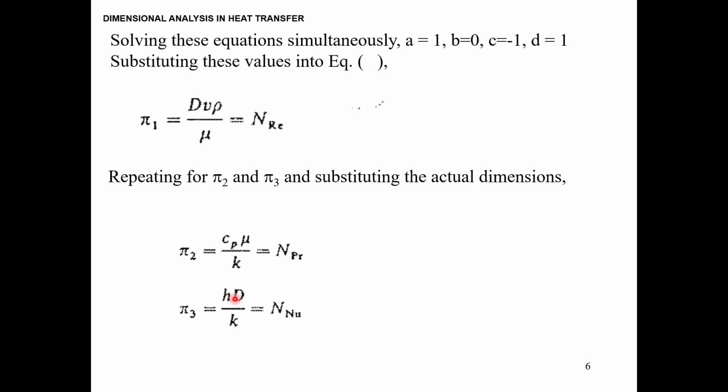To put it simply, the h you saw there was for the liquid and k was for the solid material. However, in the case of the Nusselt number, h is the heat transfer coefficient within the liquid phase, and k is the thermal conductivity of the liquid, unlike the solid we had with the Biot number. This tells the relationship of heat transfer due to convection and heat transfer due to conduction that is happening within the same phase.